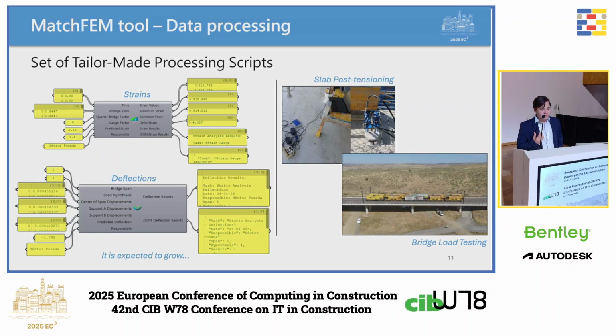So if we have IoT data, we have to process this data to gain insights. That's why we conceived a data processing module, which is a set of tailor-made processing scripts for specific applications. In this case, we have the processing of strain gauges data and LVDTs to process deflections and match measured values against predictions. This can be relevant in real-world scenarios such as slab post-tensioning and bridge load testing.